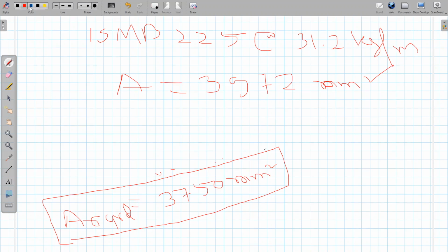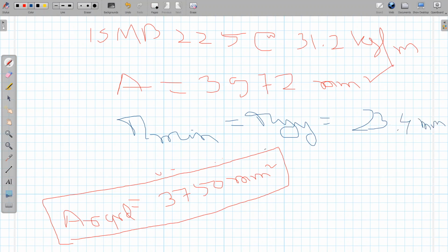So what are the other parameters that you need to know from the steel table? That is the minimum radius of gyration, r minimum. If you see this, you will find that r minimum is about r_yy, and the value given here is 23.4 mm.